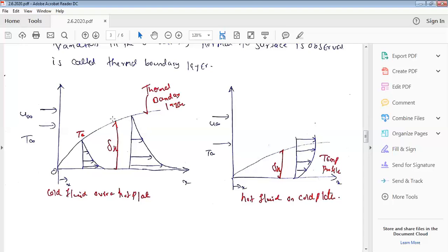That's why here the temperature profile goes on decreasing, and it comes to the normal temperature at the maximum height. This peak temperature is equal to T infinity in the open. This is at the open surface, the maximum. When you come below, to the depth of the air, nearer to the plate, the energy exchange is more. Why? Because it is in contact with the plate.